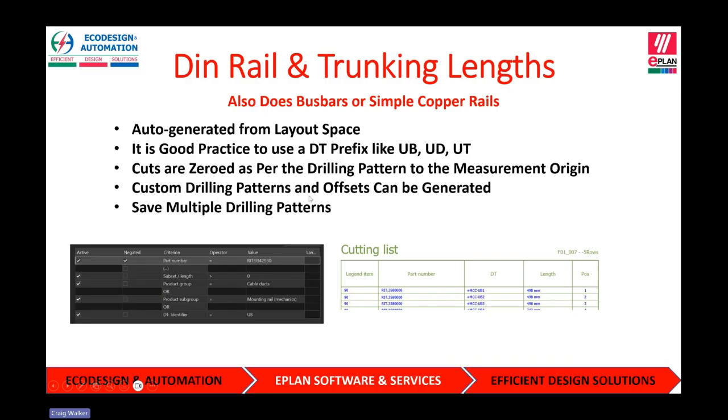Custom drilling patterns are completely producible, and it's a complex way to create drilling patterns. We can help you out with that, but it's pretty much choose your first offset on the left, choose how many increments you want to skip and then increment size, and then it can generate, and it will auto move the end hole to make sure you don't get any funny drilling patterns right on the edge of DIN rail or right on the edge of trunking.